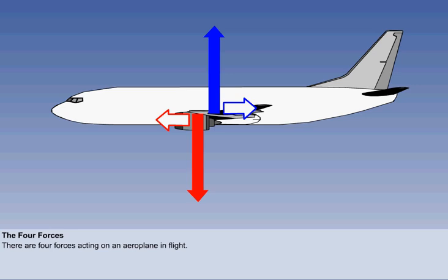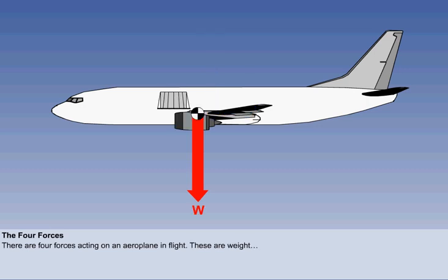We will now look at the 4 forces acting on an aeroplane whilst flying and their fundamental relationship. Whether on the ground or in the air, an aeroplane has mass, which due to the acceleration due to gravity results in a force, weight, which always acts or pulls the aeroplane vertically straight down, and weight increases as the mass of the aeroplane increases. When the aeroplane is on the ground, the surface provides a reaction, which equals the aeroplane's weight.